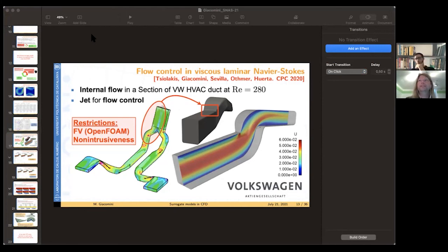Your own flow solver? The low order solver, we had some positive reviews in the sense that it's still a finite volume framework, so they are indeed interested in this kind of framework. But of course, they're not so keen to switch from the libraries that they use to other libraries. So there's the possibility. We have some ongoing work with a student trying to see whether it's feasible to implement this face-centered finite volume solver in the context of OpenFOAM. In that case, it may be of interest as well, yes. The higher order solver is a bit more green in the sense that there are some additional difficulties because, of course, higher order solver is more precise, but it's less robust.